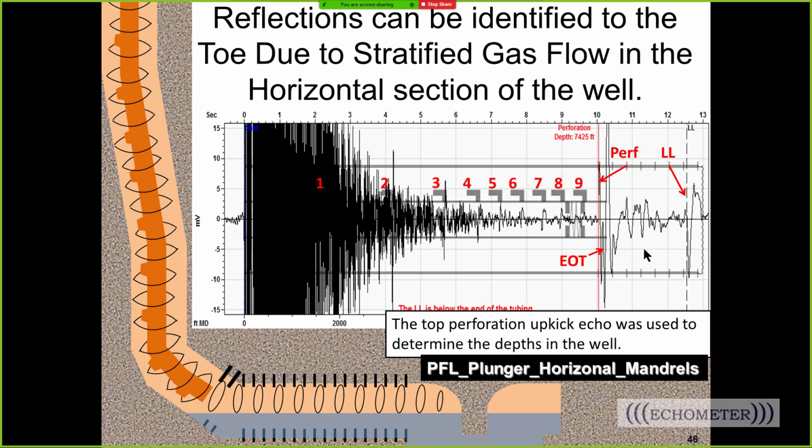And this is a well where out near the toe, there's a slight drop in the well bore where the horizontal has a trap. It goes down and comes back up, and liquid collected in a low place, and that's what made that down kick. And it's not uncommon to shoot a horizontal gas well and see all the way to the toe of the well, because a lot of these gas wells are toe up, and the liquid level is just going to drain down, and you'll see all the way if the liquid production rate's not high.